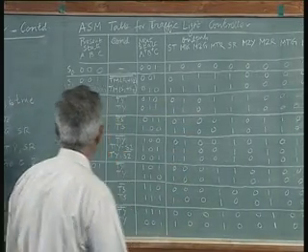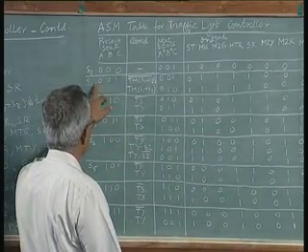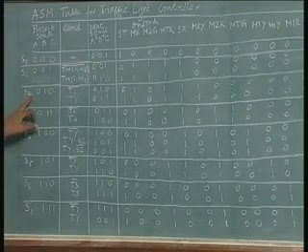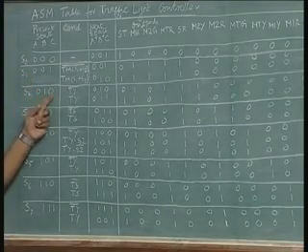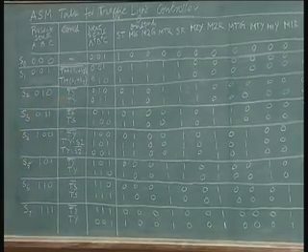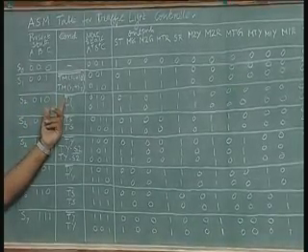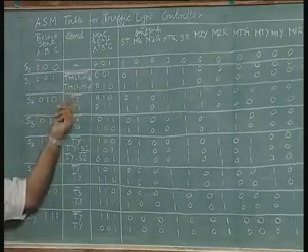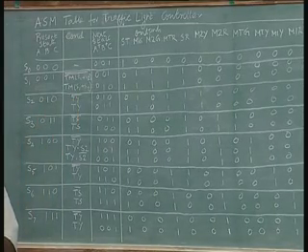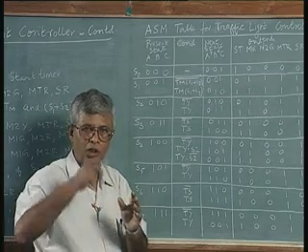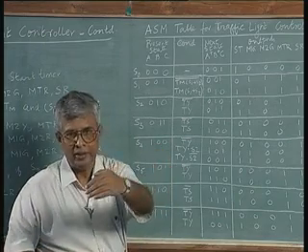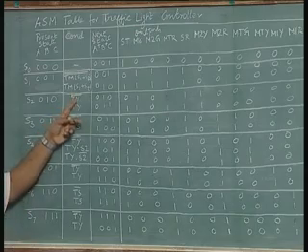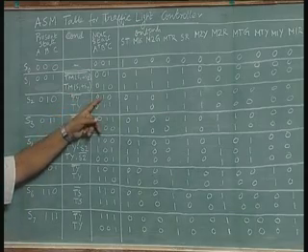For example, you can see in state 1, or make it a simpler state, state 2 which is 0 1 0, all we are looking at is yellow. This is main 2 yellow, M2 yellow. M2 yellow we are allowing for the yellow time to be over before we turn it off to red, so that we can allow the side traffic, main traffic to side road. So that is the condition here. If it is not there, you continue to be in this state.